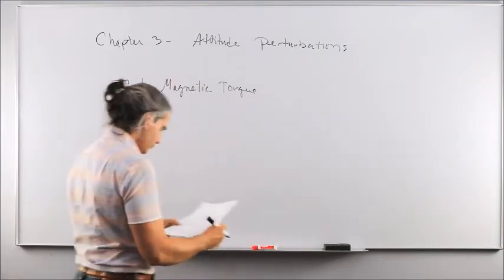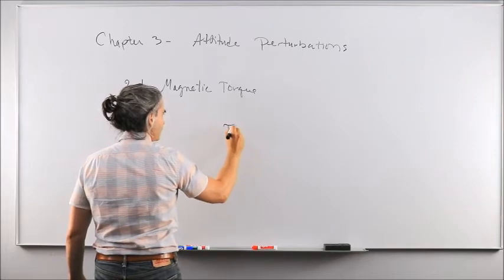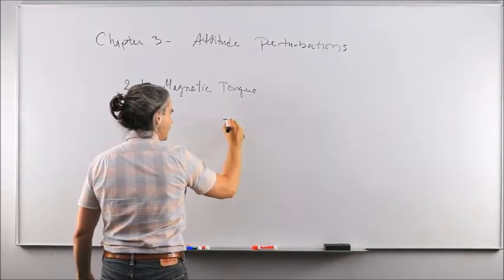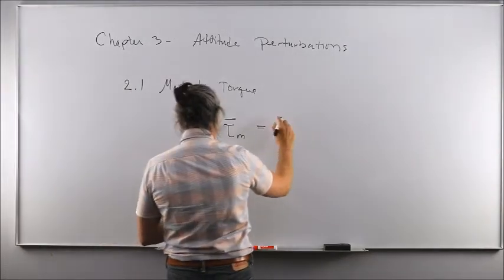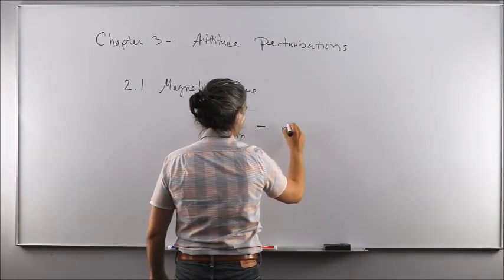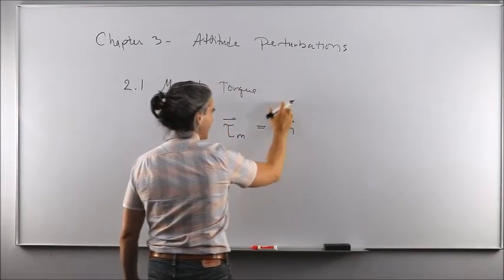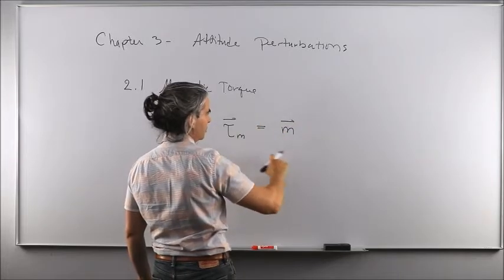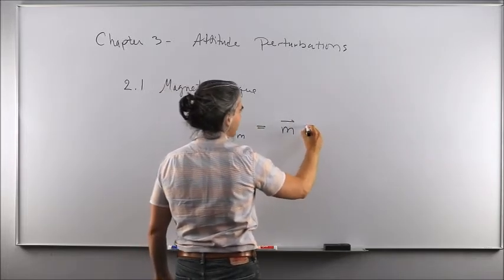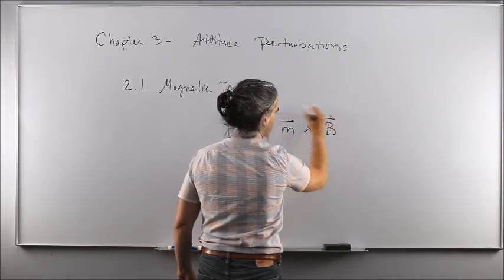So, first things first, the magnetic torque in terms of a vector acting on a spacecraft can be calculated as the interaction of the magnetic dipole vector of the spacecraft, created by the electronic components running current through the multiple wires of the spacecraft, cross product with the Earth's magnetic field vector.